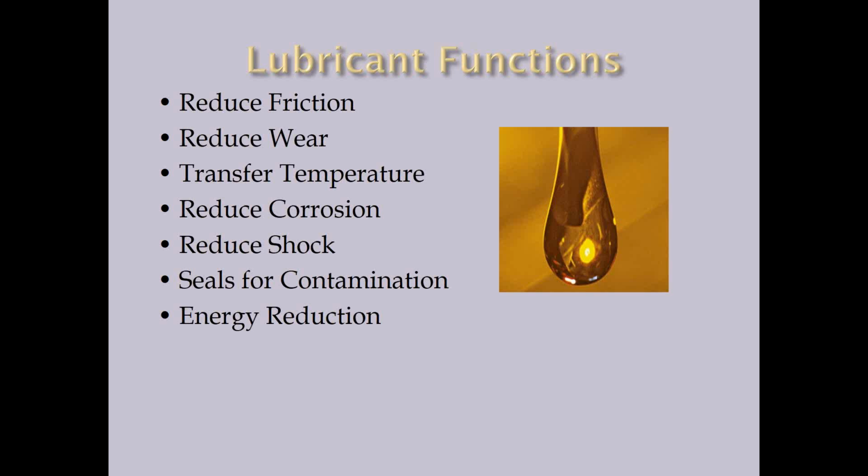And so my customers along the ocean, like down in the Caribbean, where they have pumps out by the seawater, we keep the motors greased continuously with automatic lubricators. It keeps salt water from corrosion from getting into the bearing, getting into the motor. And if we use the right lubricants, such as synthetic lubricants, we can actually reduce energy.